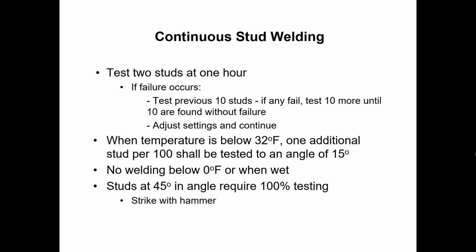Then for continuous stud welding, so say you started up at 7 o'clock and you did your two studs and you kept welding and kept welding. Every hour you need to test two more studs, basically to make sure that nothing has changed with the setup.